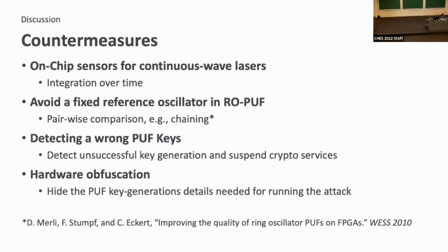We proposed countermeasures at several different levels. On-chip sensors are still promising. The one for the pulse lasers is not necessarily effective, but its extension to continuous wave laser would be possible with additional techniques such as integration over time. If we focus on ring oscillators, avoiding a fixed reference oscillator will make the attack more challenging. For example, we can use pairwise comparison.